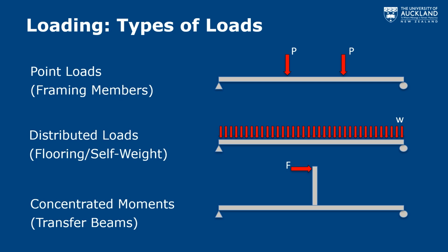That's because for design, it's an iterative process, so there's no point in going into a whole lot of detail for something which you'll have to go through many iterations of calculations for. As you'll see in the next video, we also have a lot of uncertainty around the levels of these loads, so there's not a lot of point in getting too refined in the estimates. If you think about a floor, it might be full of people, it might have no people, and those people might be of different size. So we have to average all of that out and use some simplification.